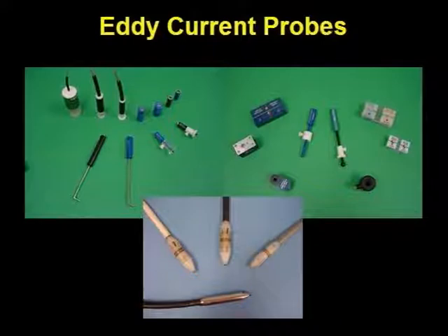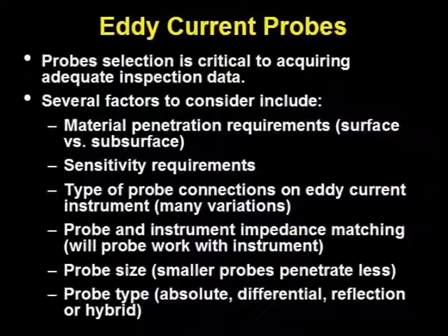Even more than ultrasonic inspection, special purpose eddy current coils are designed for specific applications. Thus, there are thousands of potential choices. Many times an application will require a special design just for the application. Some probes are point probes, some are encircling, some are differential probes, which compare the outputs of two coils. Some are side-looking for use inside holes.